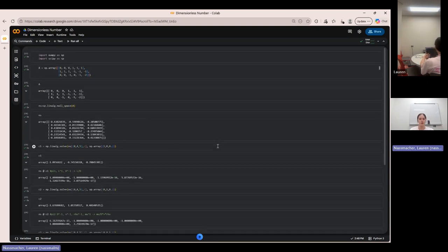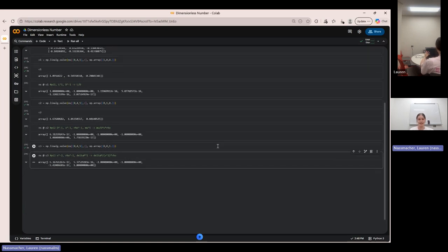Now you figured out how to solve for a null space, which is a way to find a dimensionless number by multiplying it by a matrix that you came up with in order to find, again, a dimensionless number, or for the Buckingham Pi method, 3 equations, however many equations you need at the very least, that show you how to get a dimensionless number for a certain problem that you're going through. And this one is specifically for a pipe. So we've discovered how to create a dimensionless number for the flow of a pipe.